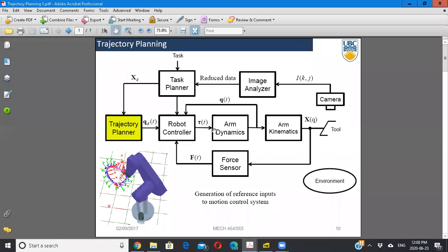That's only when the robot will rotate. Okay, in case of revolute joints, we're just considering revolute joints for this particular diagram, but there could be prismatic joints. In that case, you have to send forces to the joints. So what is a linear force for a prismatic joint? The counterpart of that is the torque for a revolute joint, okay?